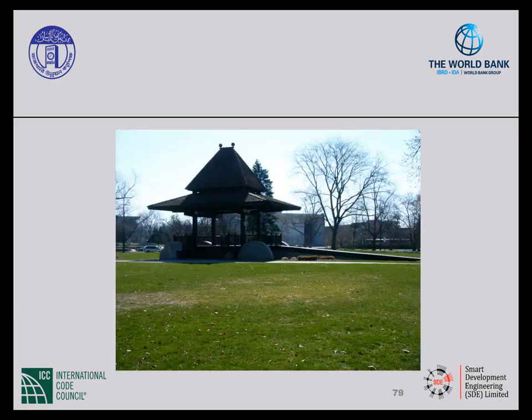Let's take a look at this ramp. What's missing? First off, there's no handrails. If there's no handrails, there's also no edge protection. And it's hard to tell from this picture, but it looks like the slope is greater than a 1 in 12. So all around, I would say this is not a good example of a ramp.